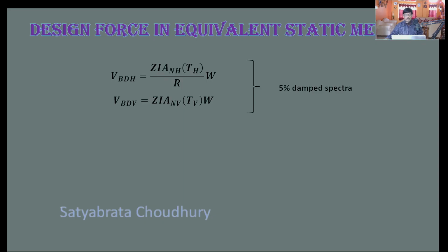It is the actual dead load in the system plus a percentage of the live load. This we shall discuss in our future videos. So this is the base shear force for which you shall be designing the structure. We shall distribute this force later on, we will see how to distribute. So these are the basic formulae for the computation of the base shear forces.